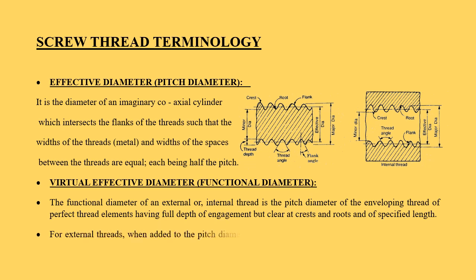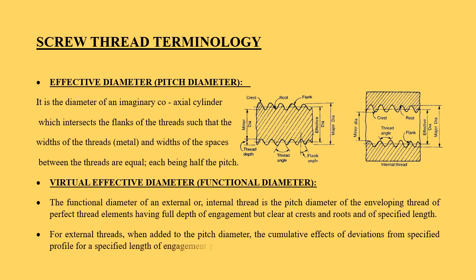For an external thread, when added to the pitch diameter, the cumulative effect of deviations from specified profile for a specified length of engagement gives the functional diameter.